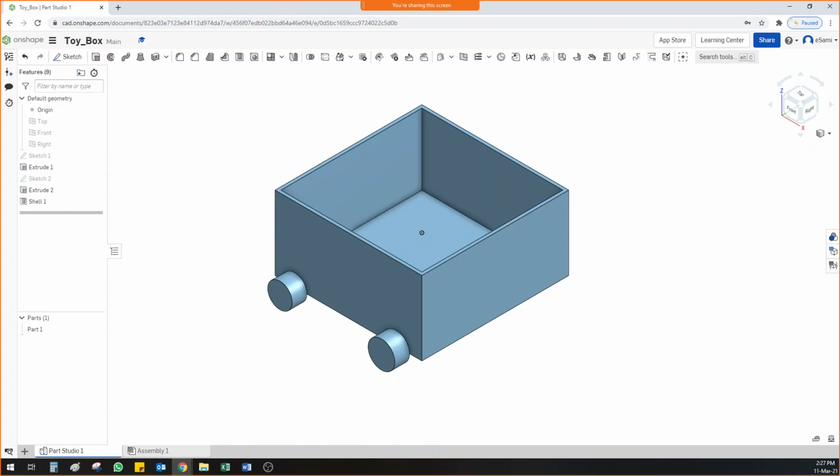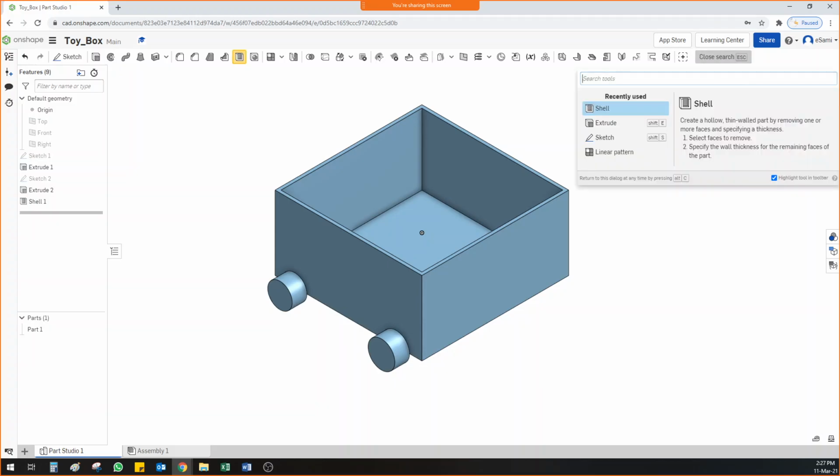So guys, so far we are following similar options as SolidWorks. How to cut a material inside, you have maybe options here to make a hole wizard, and you can use the same extrude option to remove the material. In addition, if you are not sure what tool or where to find a certain tool, you can use the search option.